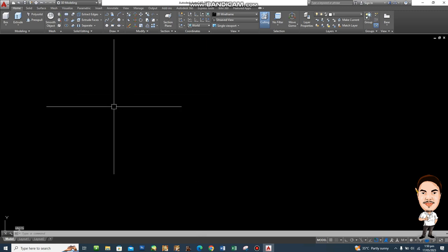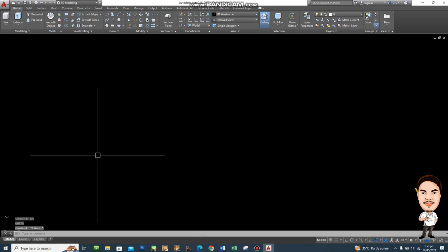Okay. So the first thing that we are going to do, just like with our plate number 21, is we have to type insert. So last time I have discussed to you how to write block the title block. This time, since we have the title block, what we are going to do now is just to type I, enter.